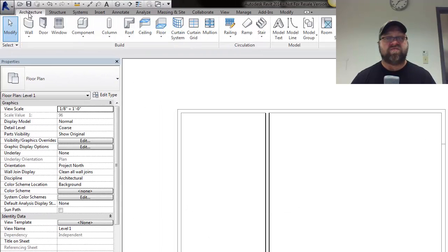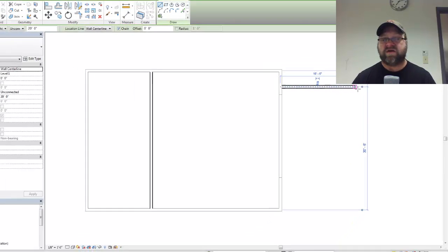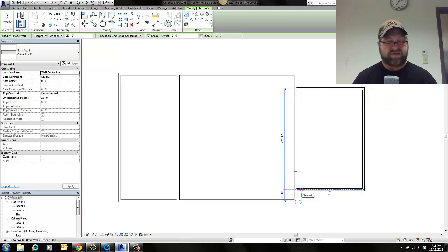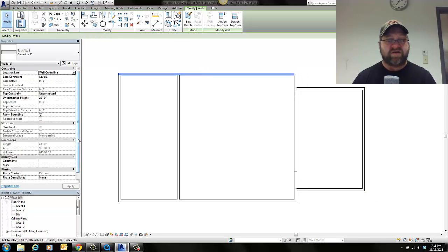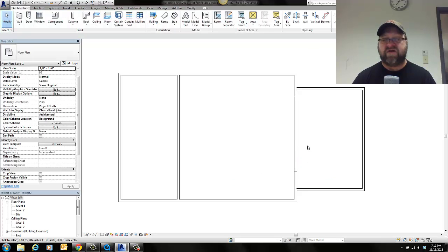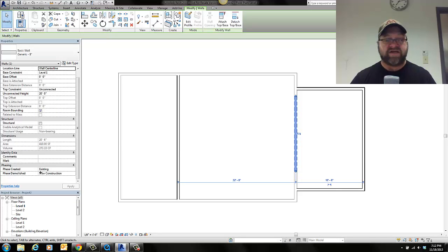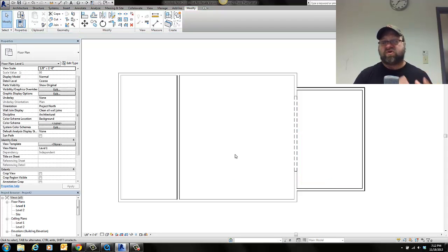And then once we make the opening, we'll have some new walls that are going to enclose that side as well. All right, so if I turn chain on, there we go. So we might have that enclosed. So that's some new piece. In addition to the phase that this item was created, like that wall there, created during the existing phase, it lists that it hasn't ever been demolished. But if I would like to demolish that item, I can set the phase demolished, or I think I can use the demolish tool. There's a demolish tool here that will let me demolish that wall. And now that item not only has a phase created, but it also gets a phase demolished parameter as well. So again, we're tracking that item's existence along a timeline.